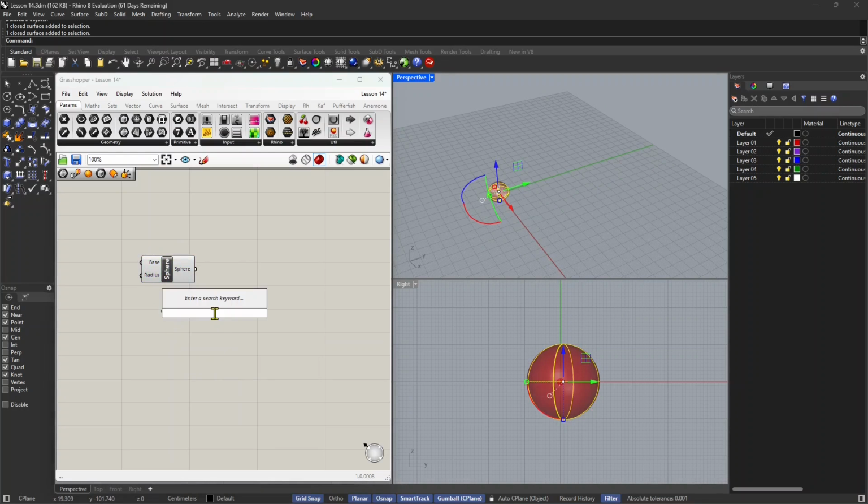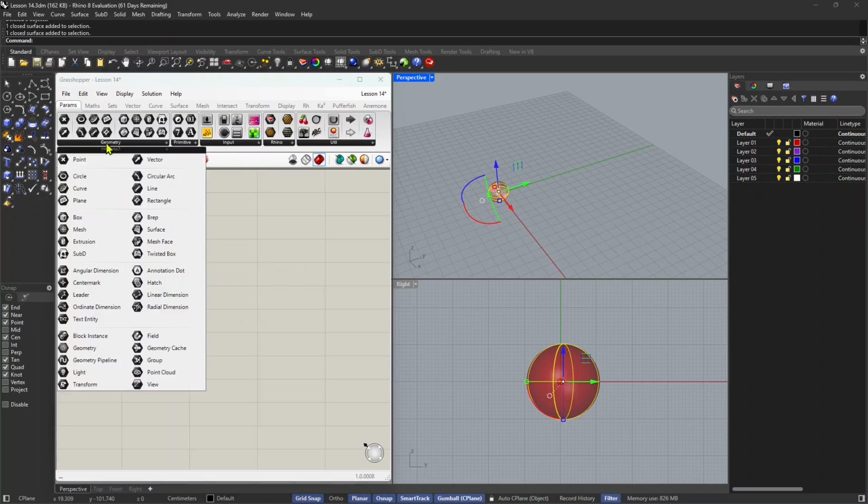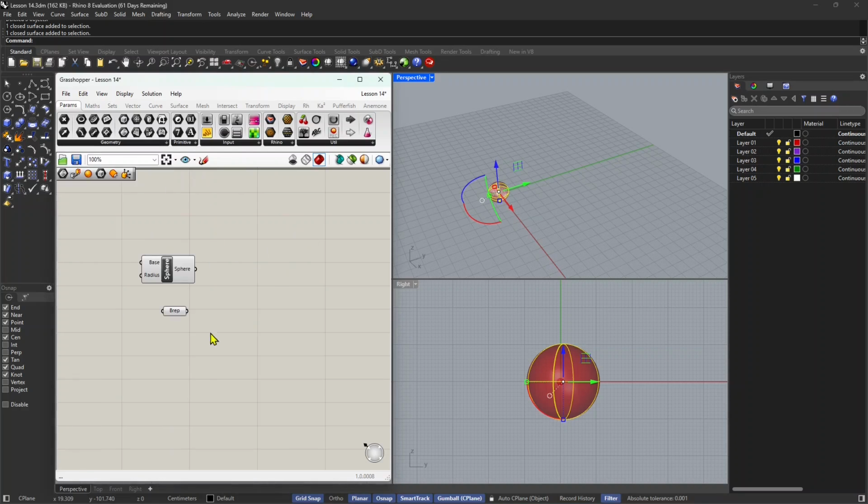You either create it directly in Grasshopper or you just use the brep. If you use any type of sphere, you cannot connect it, and there is nothing here, such a sphere that you can connect to the sphere in Rhino. So the only thing is brep. Brep is a generic shape, so you can use it with the box, with the sphere, or whatever.